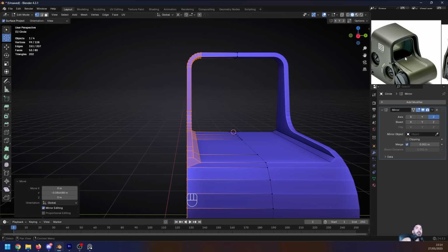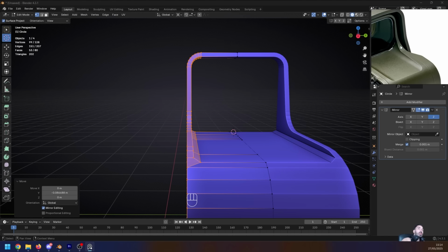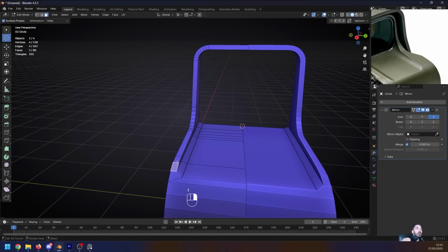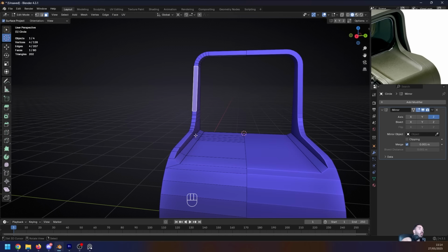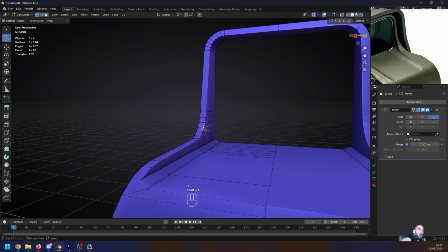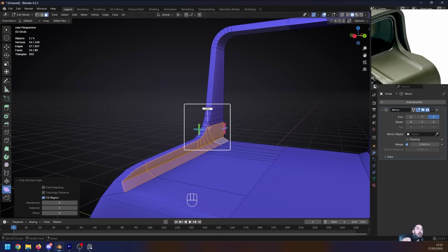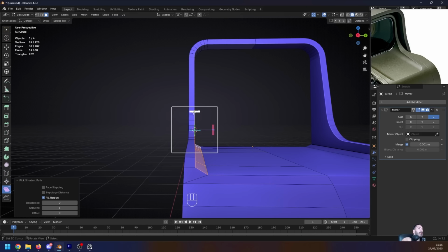That's going to make it thinner, but there's also something more that we have to do with this shape over here, because this part at the bottom has to be thicker than this part. So one way to do that is to place our 3D cursor over here with Shift S. We're going to use this menu on the side to activate our shear tool. You got to make sure that you're using your 3D cursor as your pivot point, and then select these faces underneath the 3D cursor on the inside here. And then you can use this little slider.